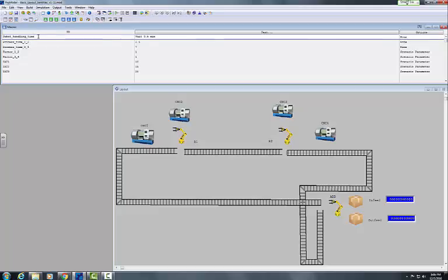So basically here we have defined a macro called robot handling time and set it to be wait 0.5 minutes. So what this means is whenever this macro is called in the processing operation, then the entity would wait for 0.5 minutes. So this eliminates multiple times of inputting the same value and saves a lot of time in debugging and saves a lot of time in doing some scenario analysis as well.